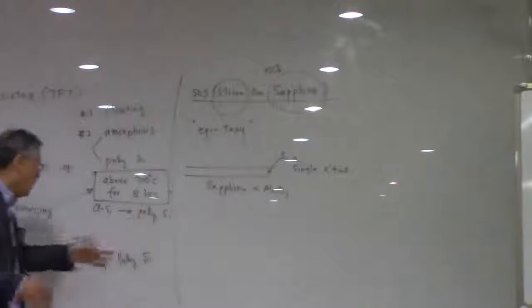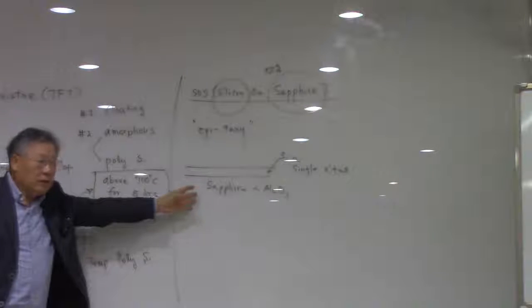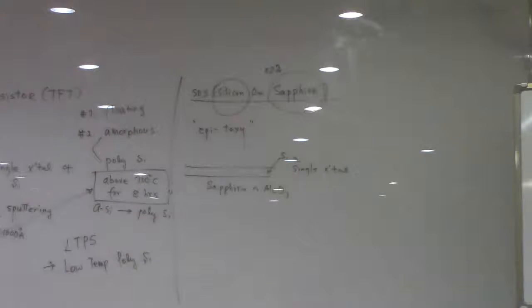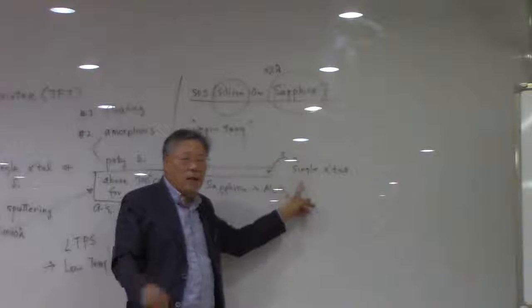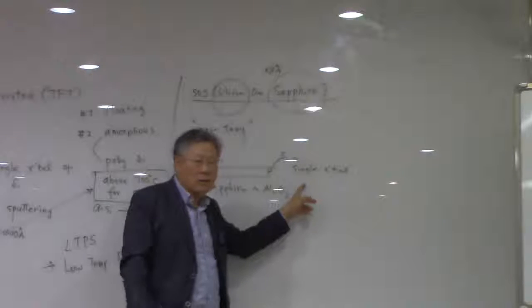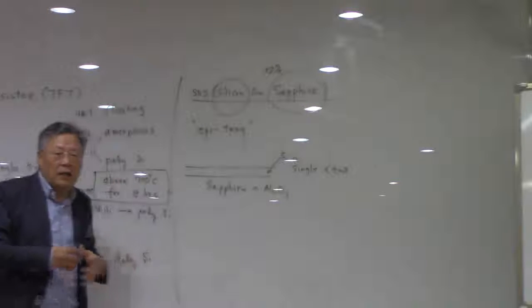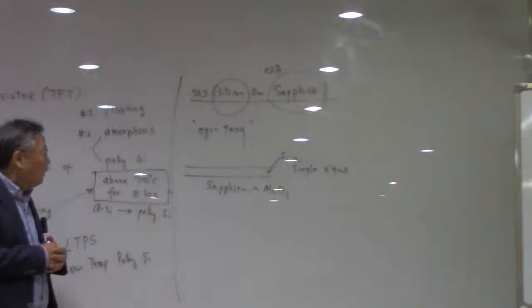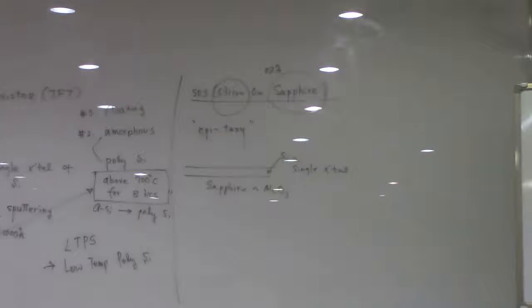So in terms of the electrical characteristics, these SOS transistors are very much like TFTs, except that TFT silicon is mostly amorphous or polycrystalline, but in the SOS, the silicon may be called pseudo single crystal, very close to a single crystal. So it is easy to extend the idea of electrical performance of transistors to this SOS, which we have discussed in the class, right?